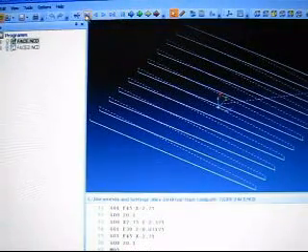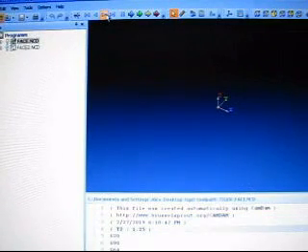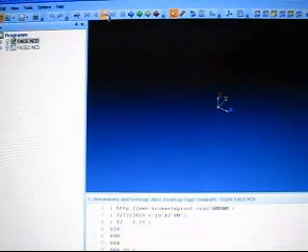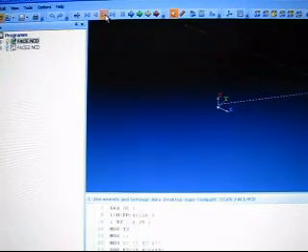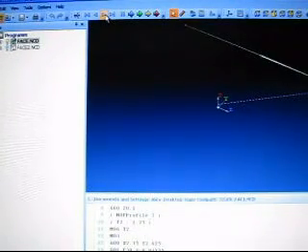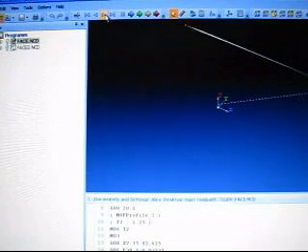Okay, so if I go ahead and step through the program, it's going to jump off up to my clearance, it's going to wrap it over, and then plunge outside of the box. Okay, I'm plunging only into the air. I'm not plunging down on my part. That's why I drew that little circle for the diameter of the tool, just to show you that. Then it's going to proceed with a cut.